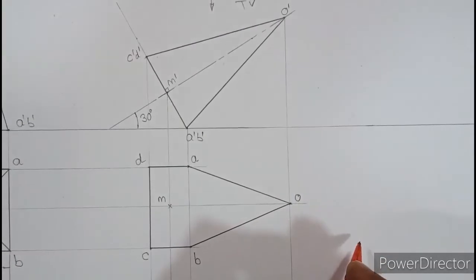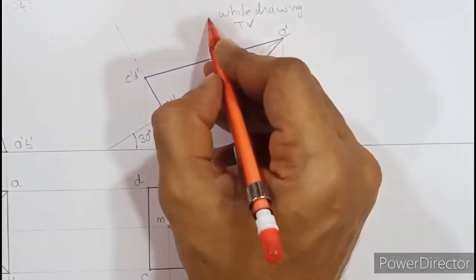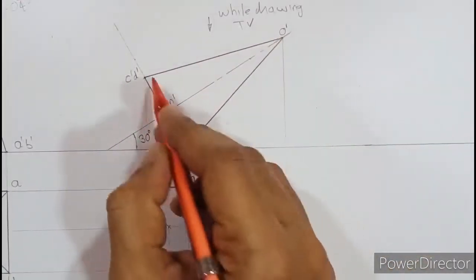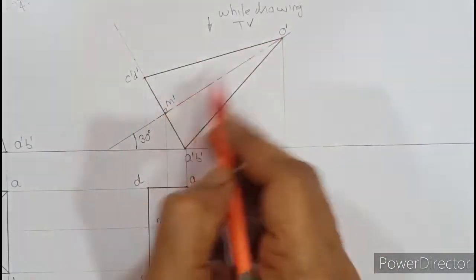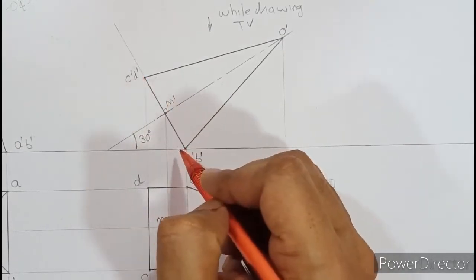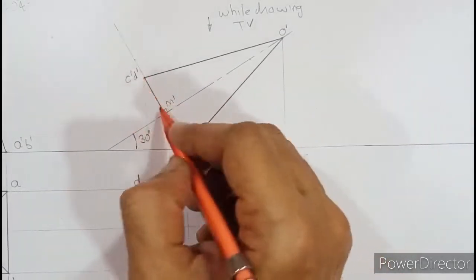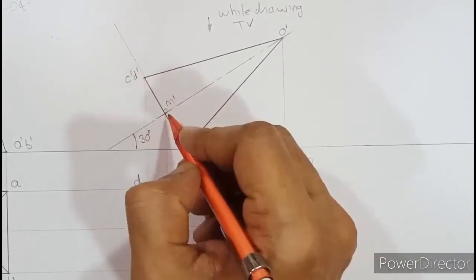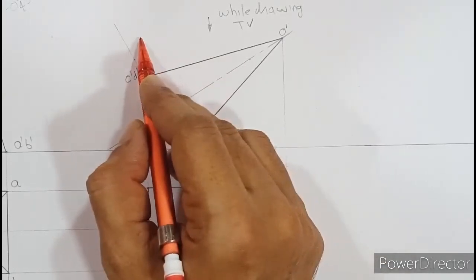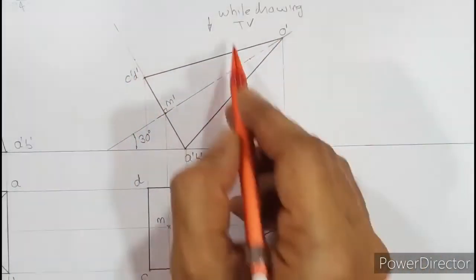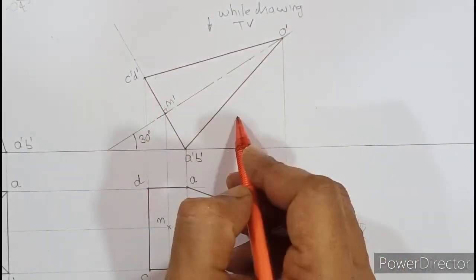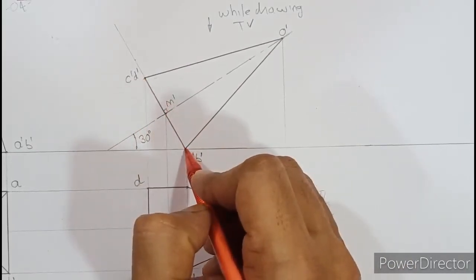Now what is step number 2? Let us see. Step number 2 is to observe looking from here. You need to compare the apex with the base and decide which is near to the observer. When I say compare the base, in the base there are so many points. So what you should do is make one CR of the base. Here, let M be the CR of the base. If you look at the locus of O and the locus of M, you need to compare from the top view and find out which is near. So here the apex is near and the base is away. And if the base is away, it will not be seen.